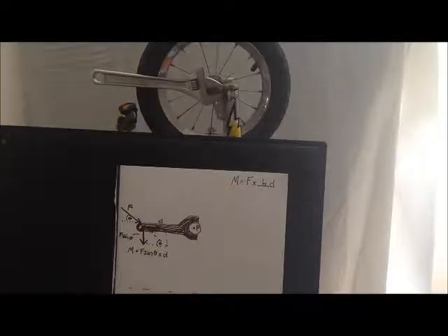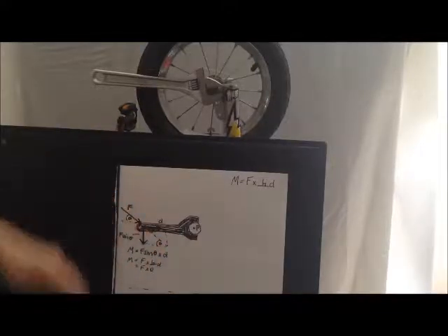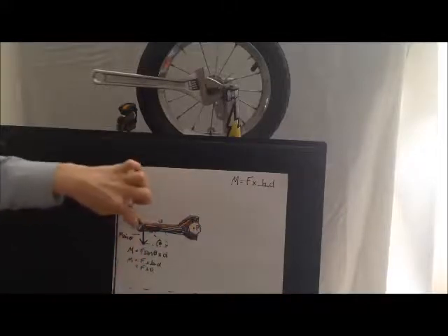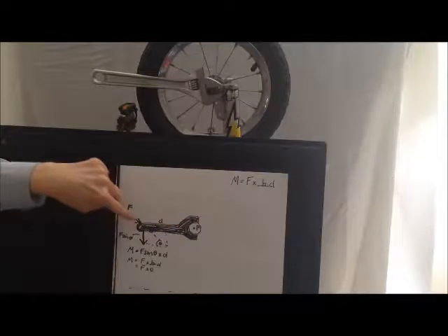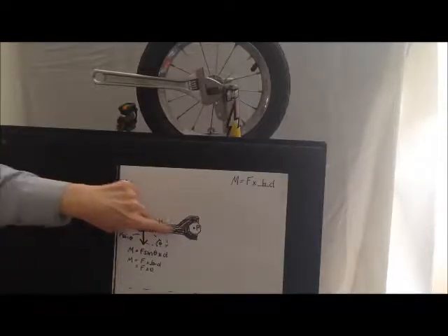And what's the moment due to the horizontal component? Well, it's nothing, because as we said before, if you press along there, nothing happens, there's no moment. We can see that because the moment is the force times the perpendicular distance, and that's 0. So the moment along here is 0. There's no twisting. So that's how to find a moment from an oblique force. You need to use the oblique force as the diagonal to work out the vertical and horizontal components at the point where the force is touching the moment arm.